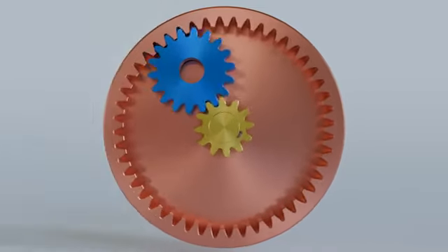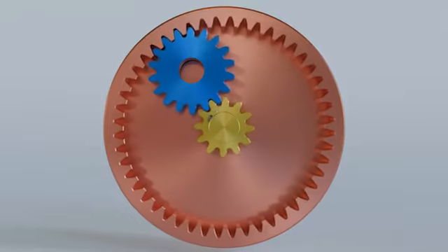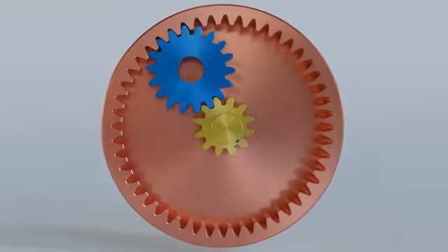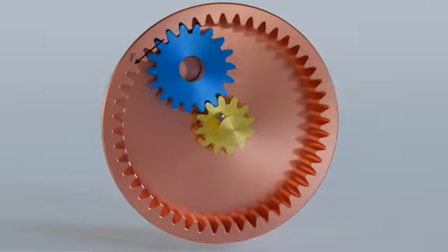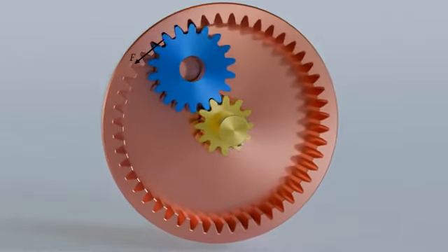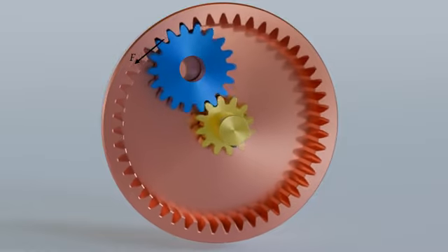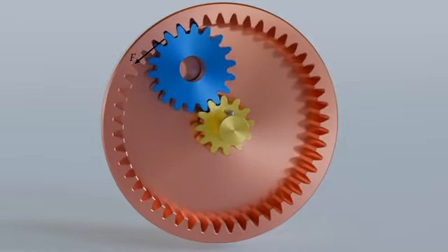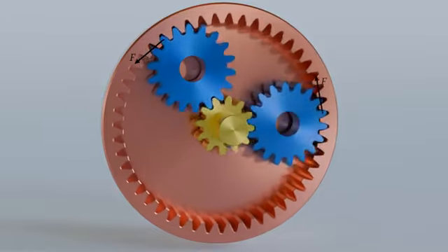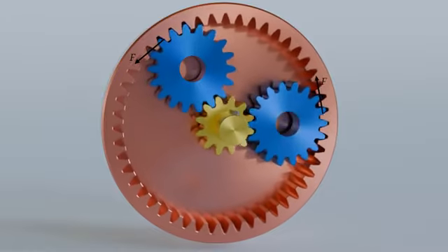A disadvantage of this gearbox is that the output shaft and the input shaft are subjected to bending due to the one-sided flank force of the idler gear. In the animation, F is the force of the idler gear acting on the flank of the ring gear. However, bending stress can be avoided if several intermediate gears are arranged symmetrically so that the flank forces compensate each other in their bending effect.